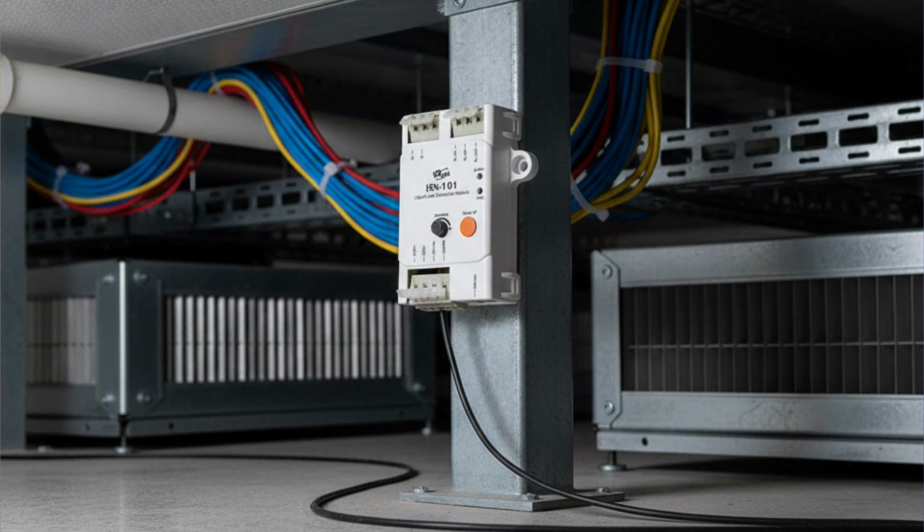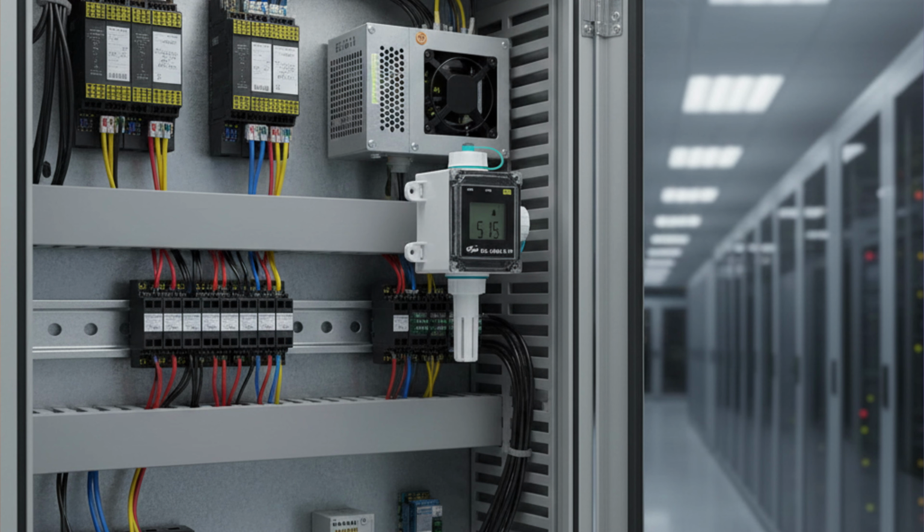In practice, this hybrid architecture shows up everywhere. Underfloor leak detection cables feeding serial into an Ethernet dashboard, rack level environmental sensors running on RS-485 loops that feed into a TCP backbone, cooling tower sensors and flow meters that still speak RTU but need to integrate into a centralized monitoring environment.